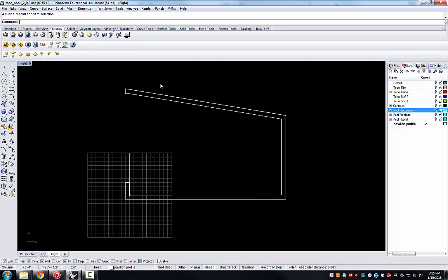I also want to do another thing before I enclose these 2 polylines and make them a single polyline, and that's to create a beam line. So I'll draw another line segment from the outside of the building down just a certain distance, holding shift to make it orthogonal. You can always click on ortho and click ortho off if you want, but I find it easier just to hold shift when I want something to be orthogonal. And I'm going to take this and offset that 12 feet to the right. And then I'm going to give that another offset of 12 inches.